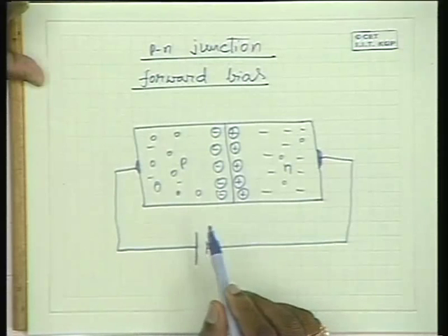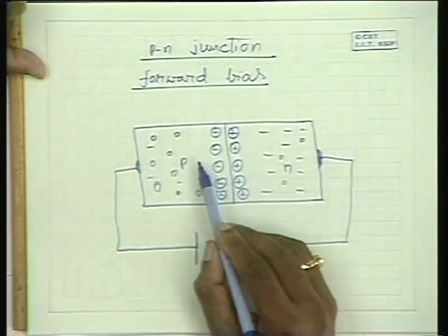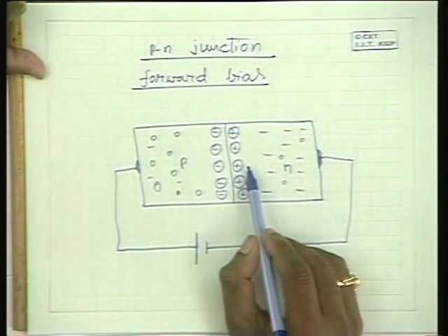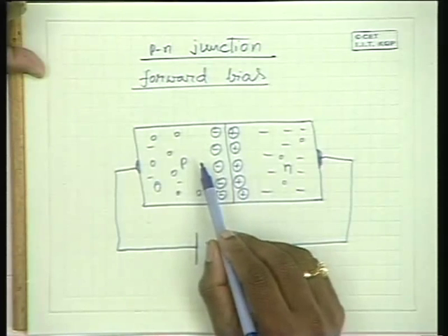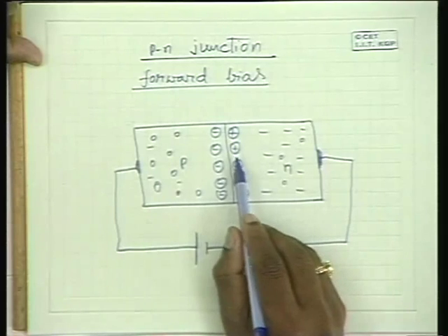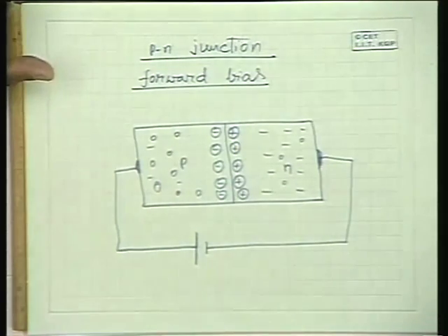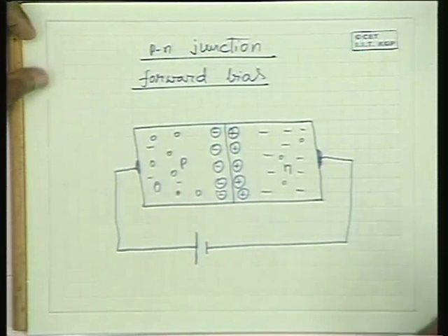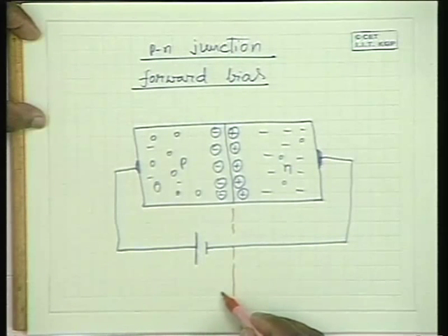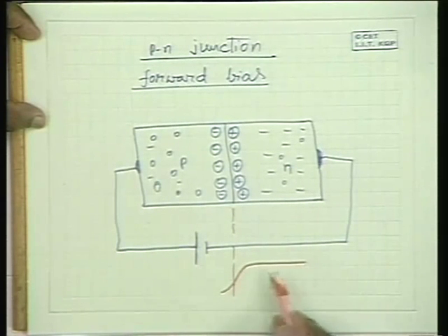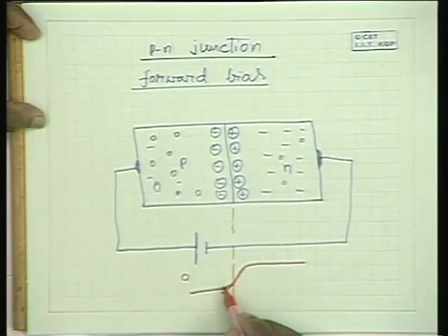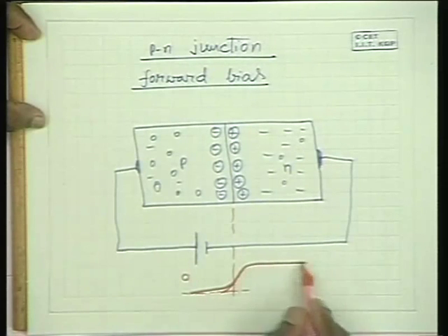The positive potential that is applied to the P side elevates its potential compared to the N side, and you have here the space charge which is already present. So if the influence of the space charge at this junction is something like this, it's creating a field of this type across the junction. For a positive charge, that is a hole, so there is a barrier like this.